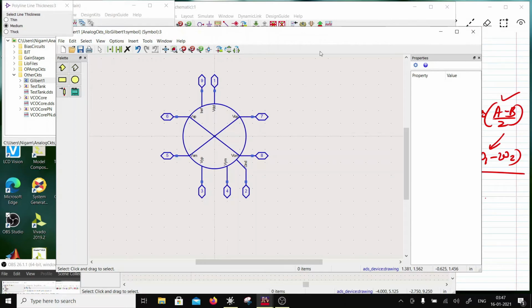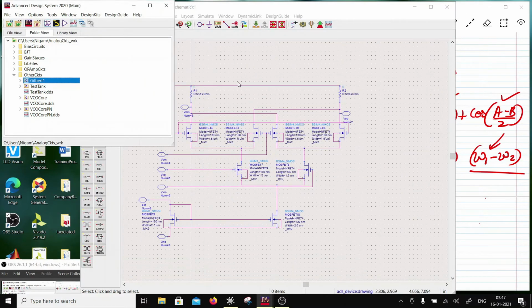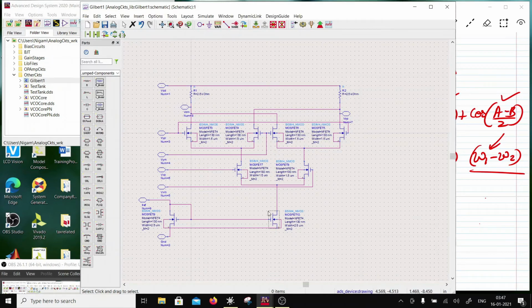Okay. So let's say if we are going to operate this from 2.4 volts, right? Now there is going to be a certain voltage VXP, VXM. So there will be a common mode voltage here, right? That will be VGS, which will be V overdrive plus VT. So it will be twice of V overdrive plus VT will be the common mode for X signal. And then you will have V overdrive, V overdrive. So thrice of V overdrive plus VT would be the common mode for VY, right? So if you are clear with that, then we can go ahead and test this one.